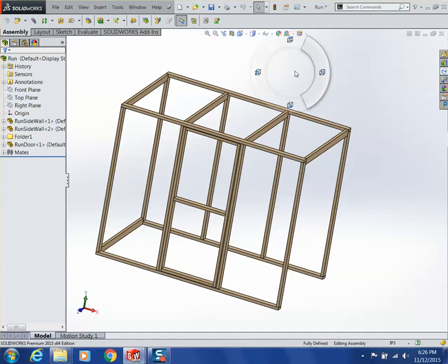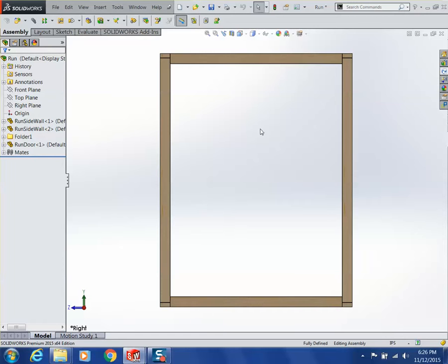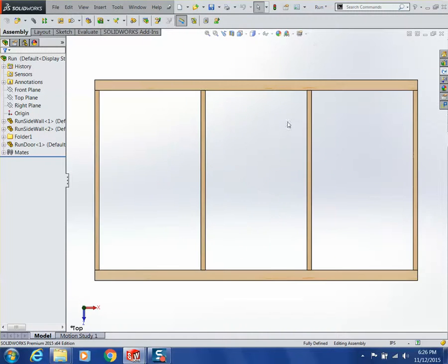So what a mouse gesture is this thing. When you hold a right click, you get this fun little wheel that shows up and gives you different options for things you can do. By the normal default, as we're looking at them here, these are just views that you can snap to. So if you run through it, it reorients your part to that view. You can also go through and set what these mouse gestures are, and you can put a macro in those positions.